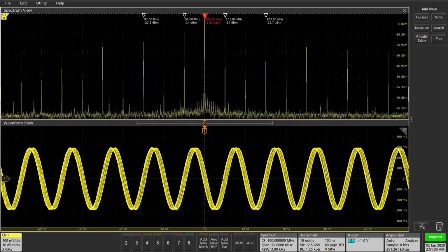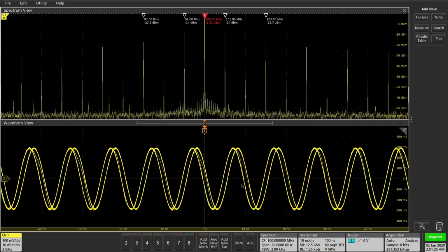Here's a square wave, and if you wait long enough, there it is. You can see very clearly two edges, and that's because it's either high or low on the square wave. Now look at the spectrum content. It's a mess of a lot of tones. That's because the square function itself has many tones. Now even though the square function doesn't have all the even and odd harmonics at the same time, you can see that the other tones are there, again due to the Bessel functions.